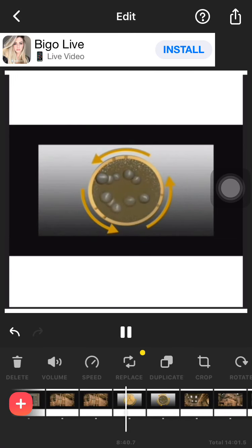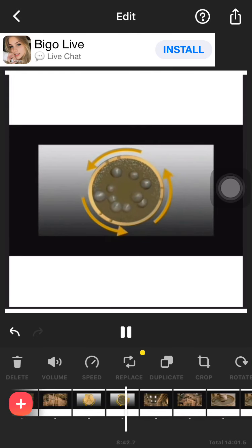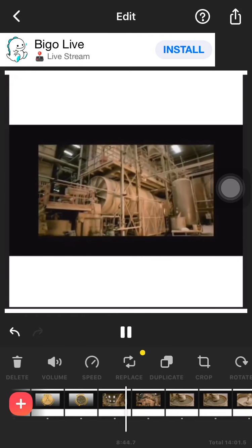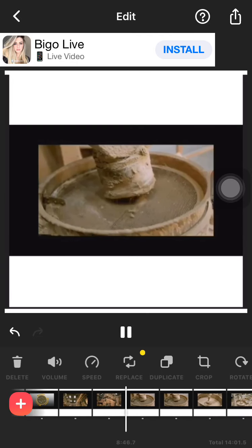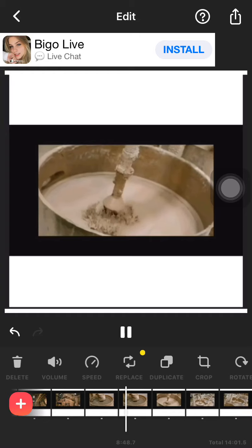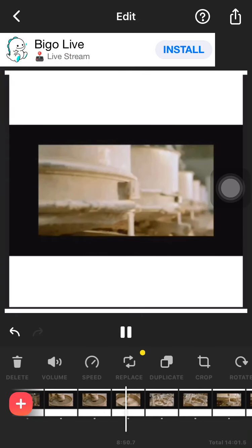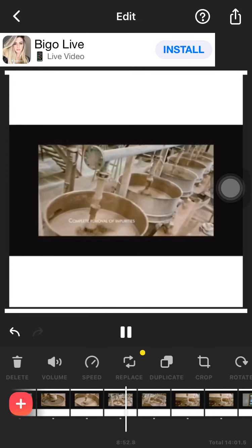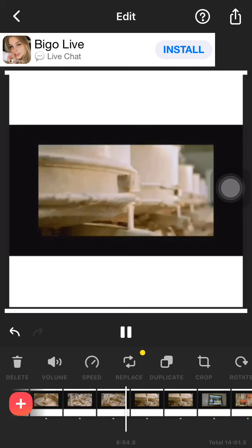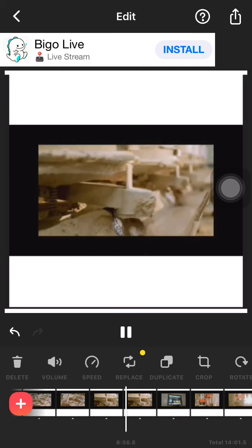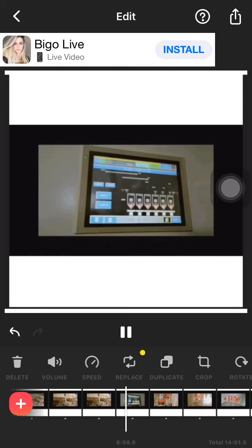Inside these cylindrical drums, giant alumina balls crush the powder to create a homogeneous paste-like mixture. The finely crushed slurry is then passed through a vibrosieve to remove uncrushed particles and then magnetic purification to remove magnetic impurities. The next step is drying.